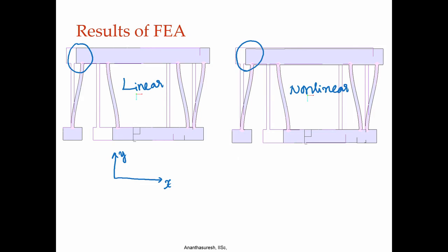It is very important in this particular example, because the reason we go for the folded beam, which is folded back here like that, is that this platform, if I call it platform 1, is going to undergo in reality both motion in the x direction and a little bit in the y direction. To compensate for that, we introduce another one, folding this beam back here, so that when this platform comes down, as you see in the nonlinear analysis, the other one compensates.